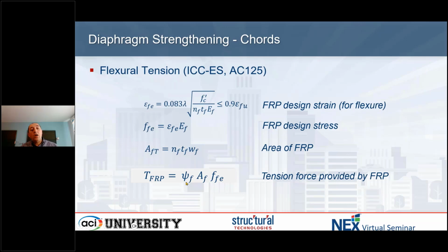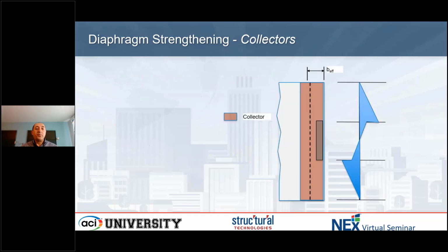Reduction factors are different from standard to standard, code to code. For example, if I'm designing per ASCE 7, I may need to apply a reduction factor. If I'm using ASCE 41, I may not need to use a reduction factor. I may need to just use 1.0 for all these reduction factors. So again, it depends on the analysis type, the codes, the standards that are controlling the design.